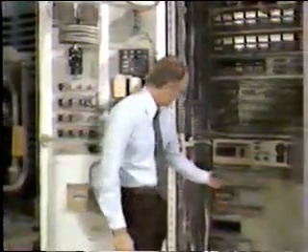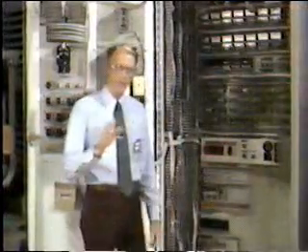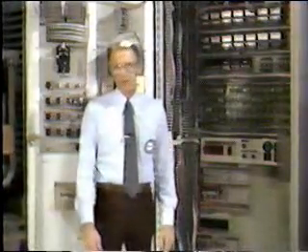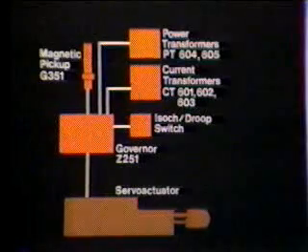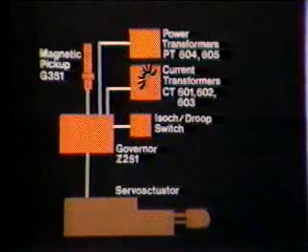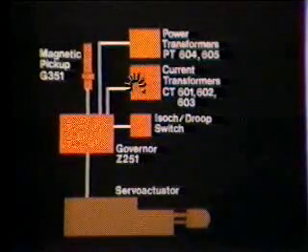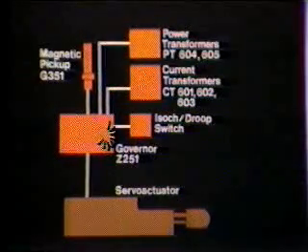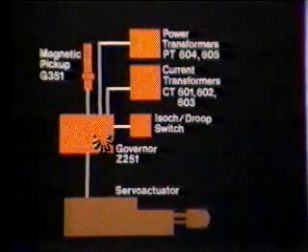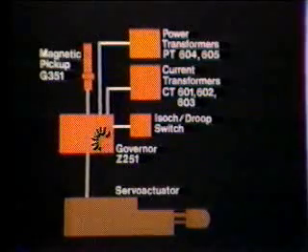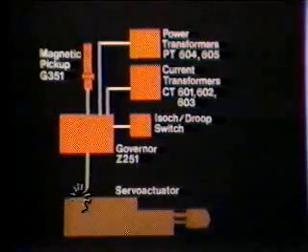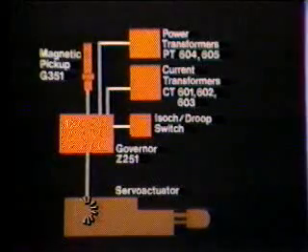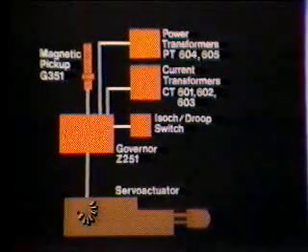Now, during parallel generator operation, the governor maintains equal load sharing between the generators. Signals from the 3 current transformers are sent to the load modules of the governors, indicating generator load. If the load module senses that one of the generators is carrying too much load, the governors will send a signal to the servo actuators to change the amount of fuel being sent to the engines.